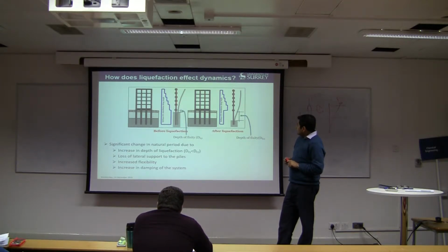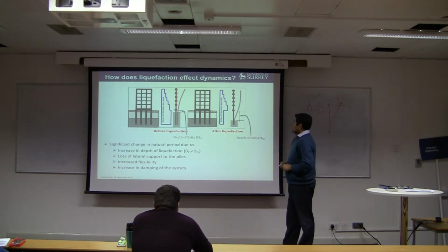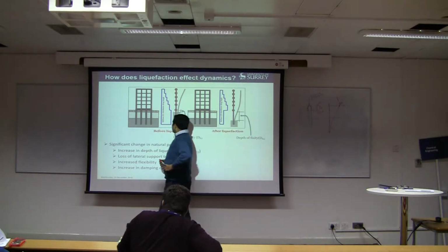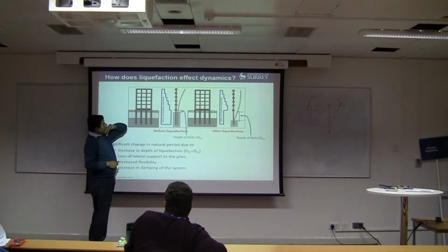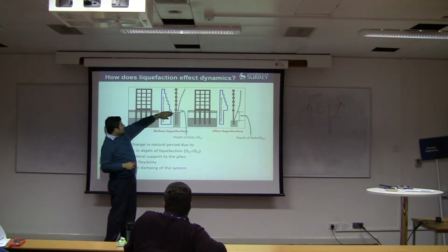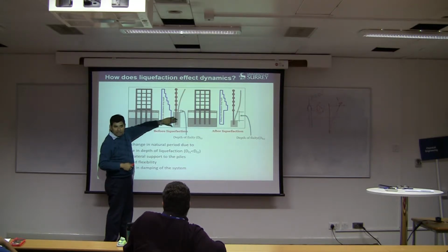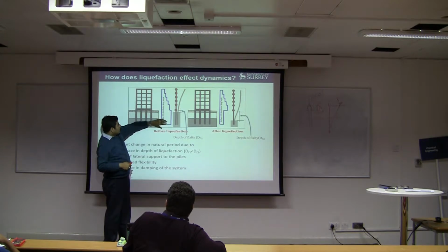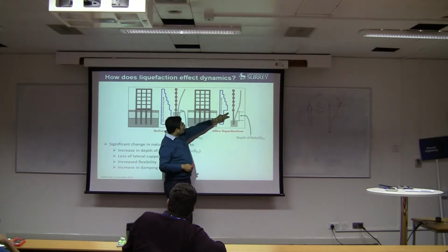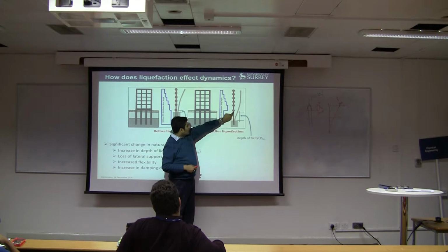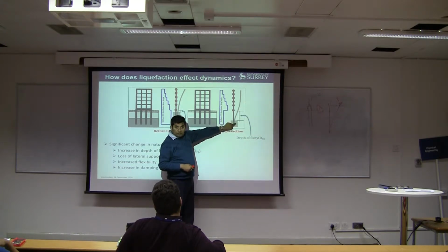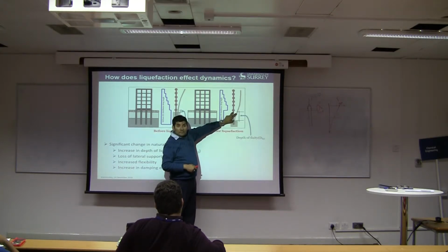If you look into the whole building, before liquefaction you have a very stiff ground, and that's why the building period etc. doesn't consider the foundation. But when the soil liquefies, you suddenly see a drop in stiffness, because this now acts as a long unsupported column, and the length is long, isn't it?